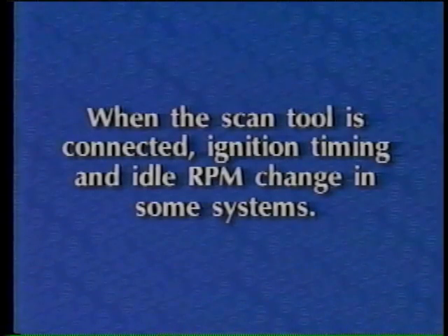And when the scan tool is connected, ignition timing and idle RPM change in some systems. These changes have to be taken into consideration during diagnosis. Now that you have some background on scan tools, let's move on to scan tool usage.